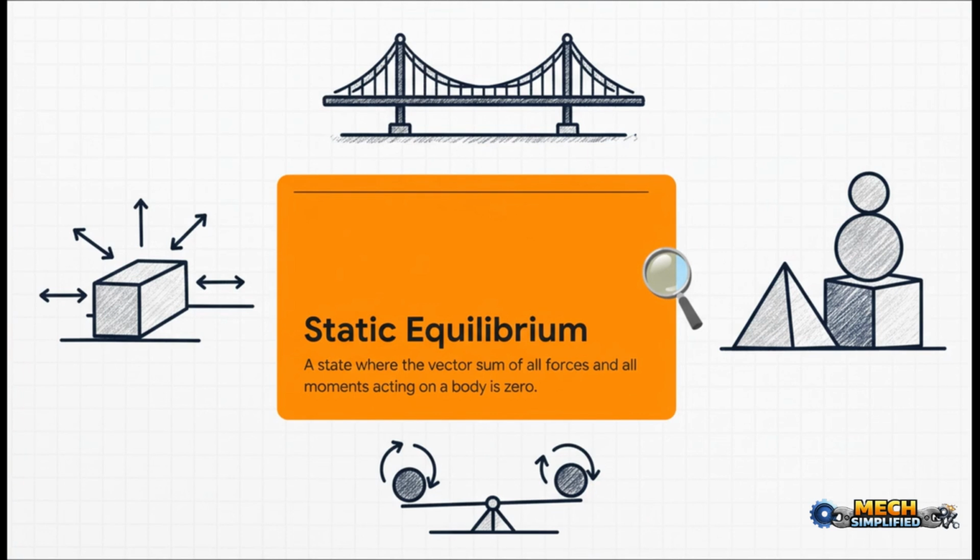The whole idea, the core principle here, is something called static equilibrium. It's a simple but powerful concept. For an object to be stable, to not move or break, all of the forces pushing and pulling on it, and all of the twisting moments, they all have to perfectly cancel each other out. Their grand total has to be zero. This is the bedrock rule for designing any strong, stable structure.